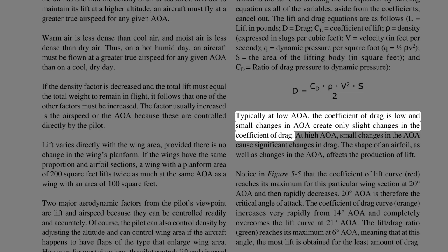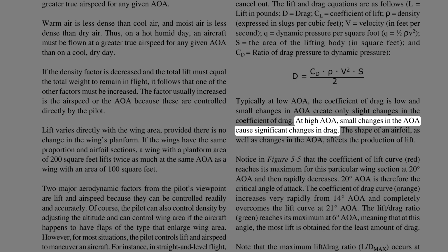Typically at low AOA, the coefficient of drag is low and small changes in AOA create only slight changes in the coefficient of drag. At high AOA, small changes in the AOA cause significant changes in drag.